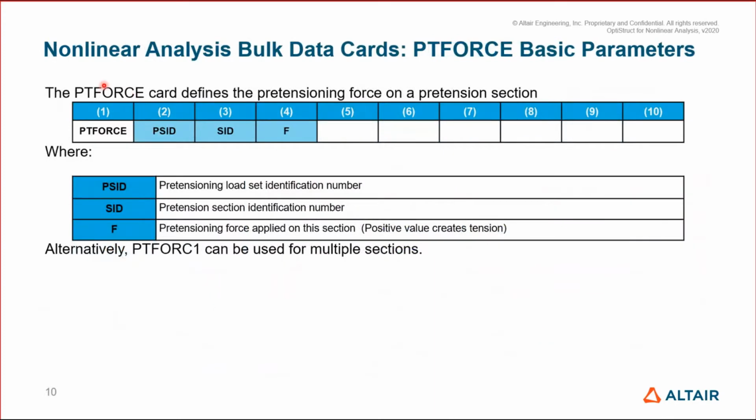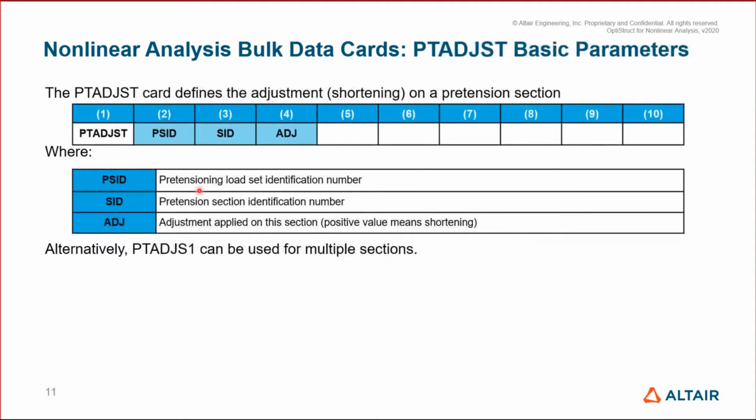If you're using force to define the pretensioning, we create this PTFORCE and then define the pretensioning force. If you're dealing with length adjustment or shortening, then we use this PTADJUST.